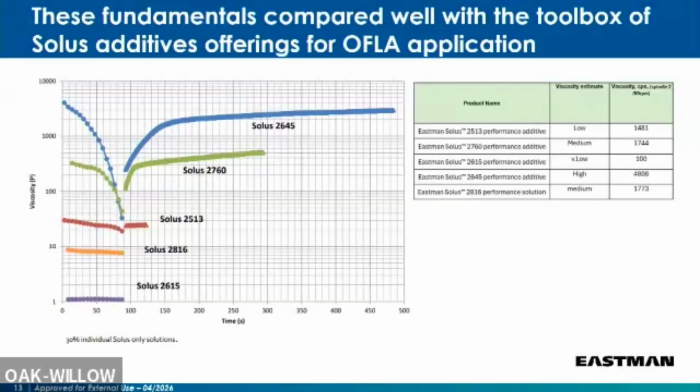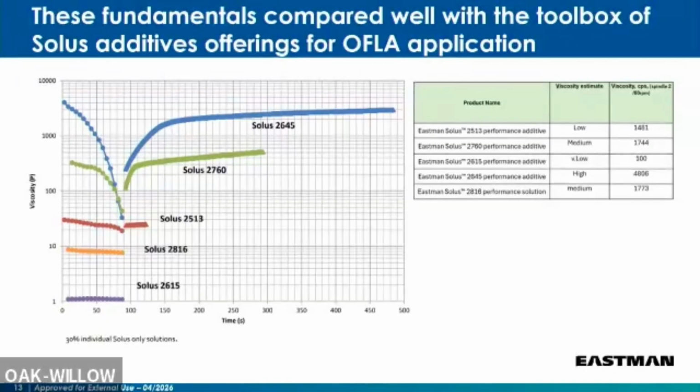If you use traditional flow additives, it will be like this. They'll flow nicely, but if there is no recovery when the shear is removed, you may end up with sagging. So you have to have this recovery. The moment the shear is taken away, the paint should recover.